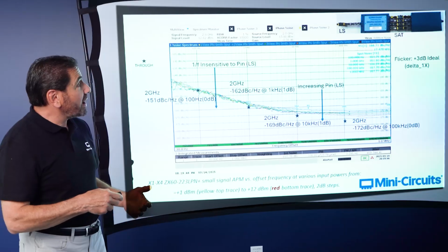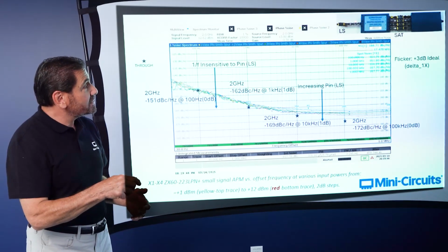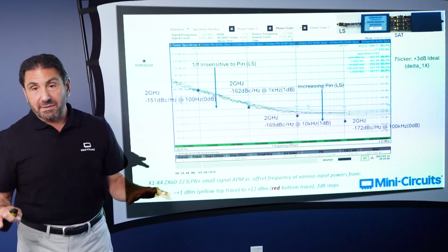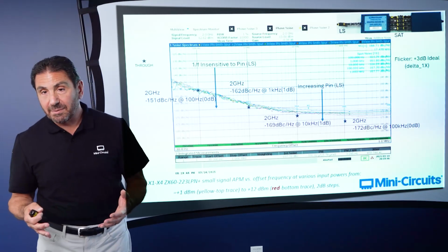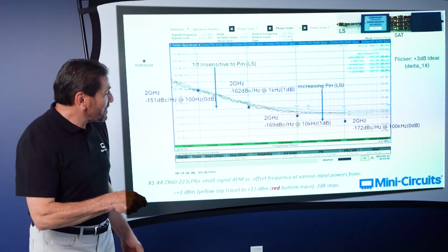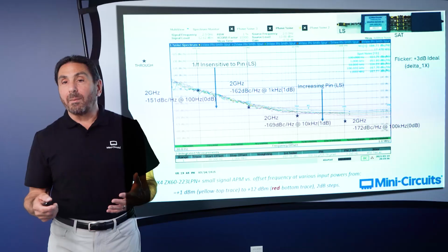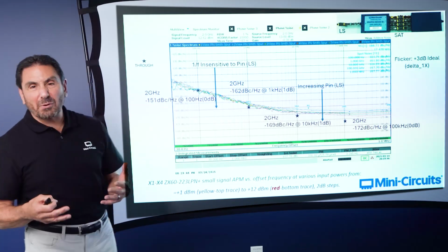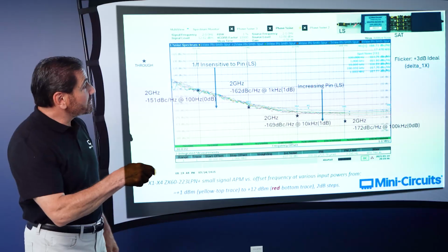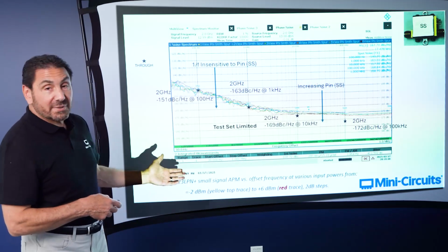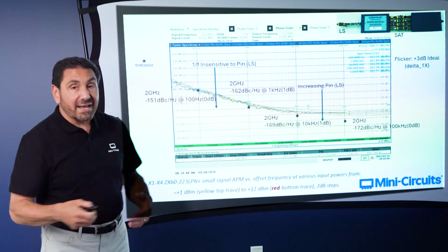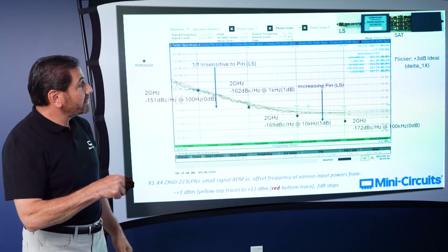But now we're going to drive the 4 with a 1, again, through a 0 dB pad. And what do we see? Again, at 2 gigahertz, we have a lot of freedom to choose power levels because we're not really influenced by AM to PM distortion. So again, if you want a nice 1 watt amplifier at 2 gigahertz, this is not a bad way to achieve that. And look at this. You're basically not seeing the degradation from the 4 parallel combined amplifiers, which is what we said. We're going to see that they don't degrade the performance because we're going to cascade it with a single. And what do we really see? Basically, the performance of the single stage here. So from that, we can infer that this combination is really not degrading the cascade, and it's being set by the performance of the first.